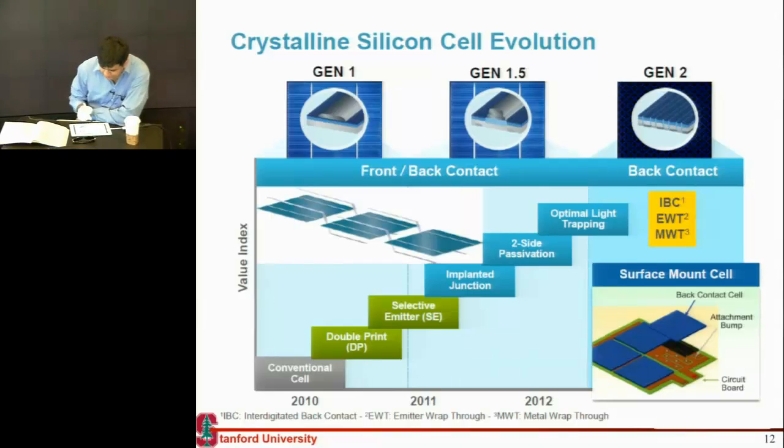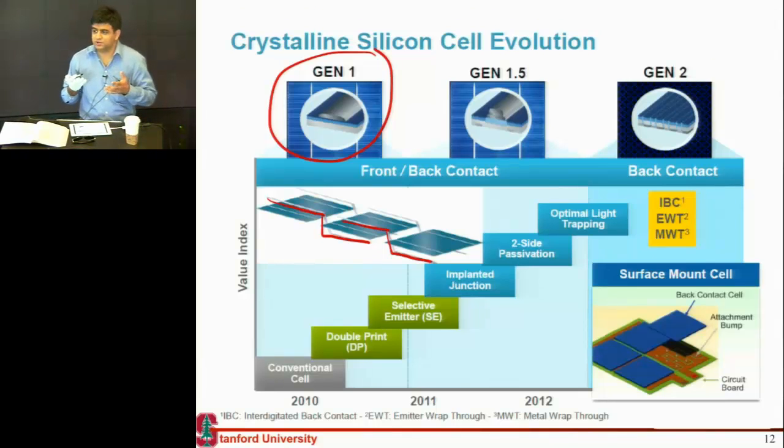So this is where most of these Gen 1 systems stand. They are connected like this, where you have this bus bar and it needs to connect the top of one cell to the bottom of this other cell. And just making that, as you'll realize when you do your project, is something where you can easily break a module, or you could have improper connections.